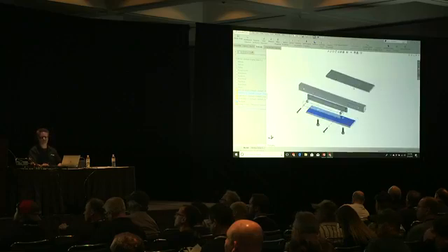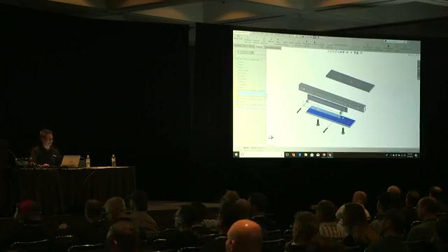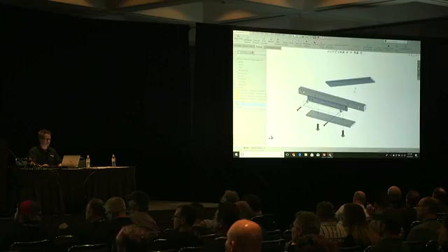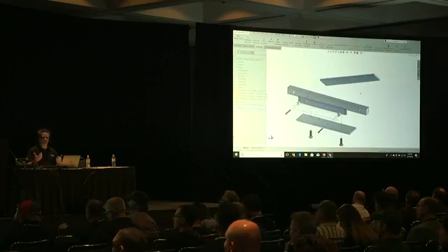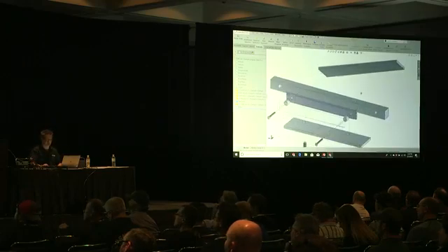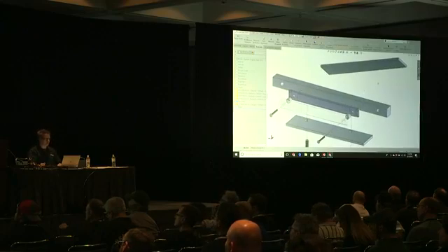There we go. So in my best FM radio voice, and we're back. When in doubt, reboot. This was one that surprised me. One of the guys that I know didn't know about this: when you have a loose part in the assembly, it's not mated. When you hold your right mouse button down, it rotates that part. It's another one that I assumed everybody knew.